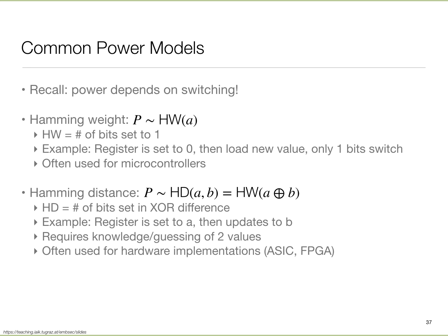So for example, I do the regulation of the frequency, which is actually core to the Linux OS, for example. I add to it a random component in an attempt to obfuscate what the adversary is going to be able to see. I've seen that work. The only issue there is that it's acting at a slower time scale. Here we were talking about instructions and all. Those things usually operate at tens of milliseconds, because they're dealing with thermal things. So just a different time scale, but the concept remains.